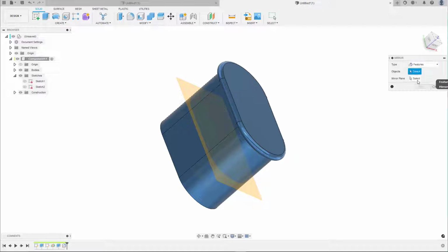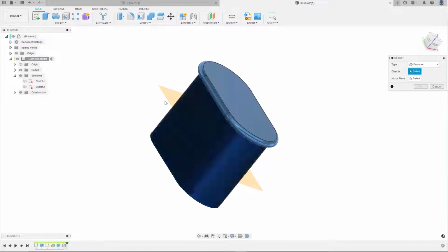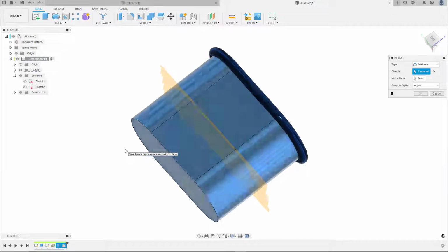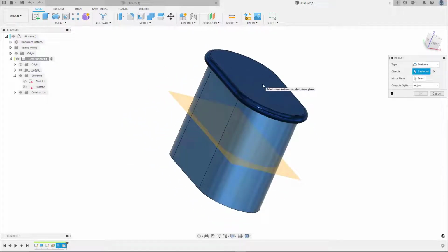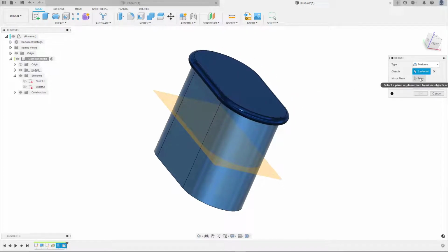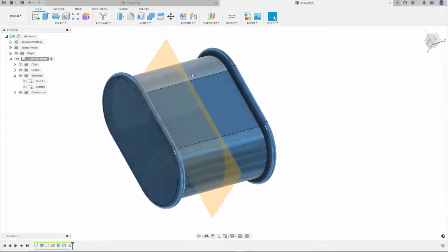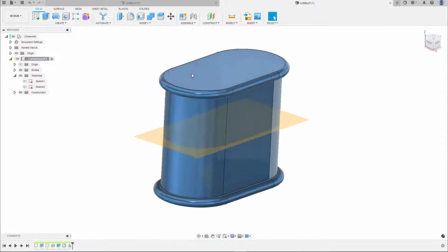We're gonna choose the feature, okay? And I'm gonna use the extrude, which is just the size of the extrude, and hold shift and choose also the full round fillet. So now I can see that my full feature, so the top part, is selected, and I'm gonna say mirror that from this plane, and then the part just gets created like that magically.